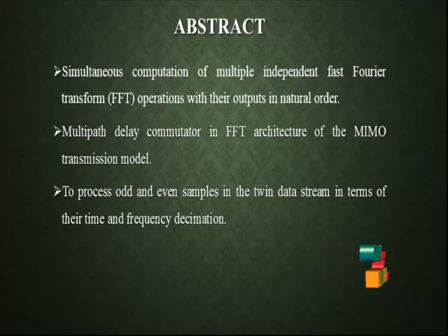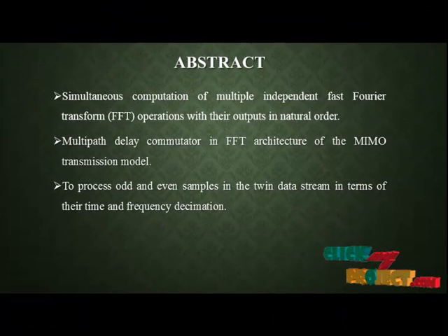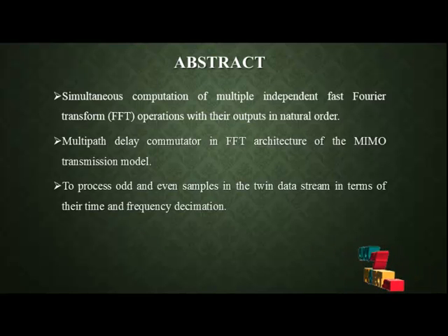in the FFT processor. The proposed architecture is designed to process two independent data streams simultaneously with less number of hardwares. The odd inputs, which are in natural order, are first bit reversed and are then sent to the FFT processors, and then the even samples are next bit reversed and they are sent to the DFT processor. The process of odd samples and even samples decimation are carried out in terms of their clock cycles.